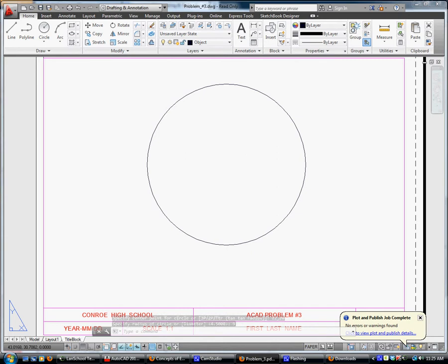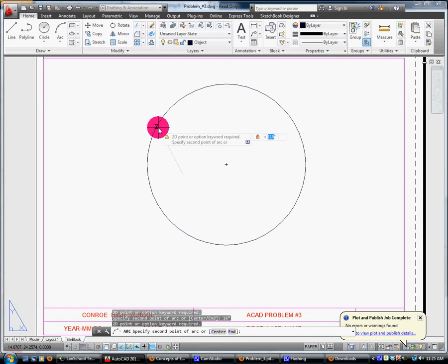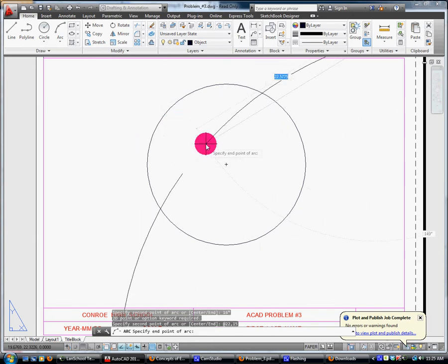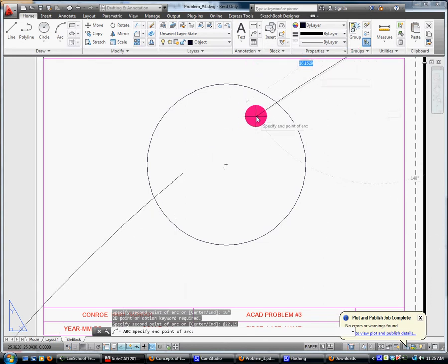Alright, now we want to draw an arc. And I'm going to show you something. We're going to do a 3-point arc again. And I'm going to type in my coordinates. And I'm going to do this on purpose because I want you to see what happens. Notice how it's going way off. This is one of those times where the dynamic input, those little floating boxes, is not our friend.